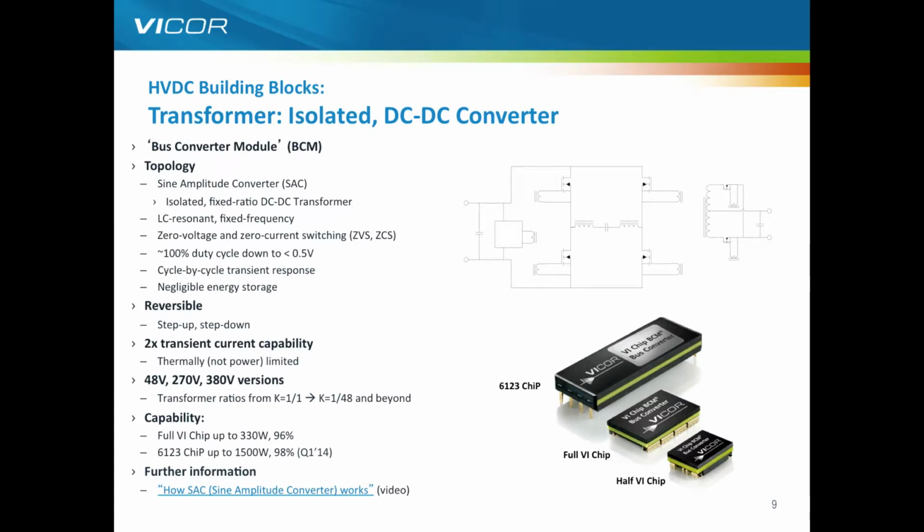So this is a real transformer. The device is made of, again, the high layer count PCB. The layers of the PCB act as the primary windings. So we go around and down, around and down, around and down in the PCB with the planar magnetics either side, and again the active silicon to control the current.